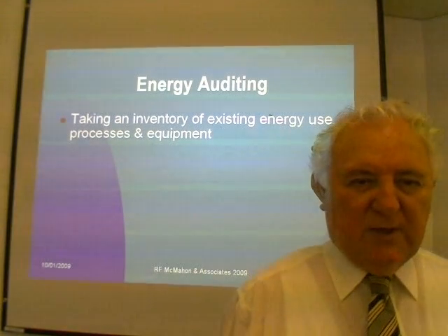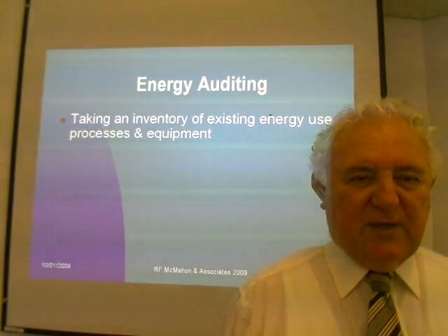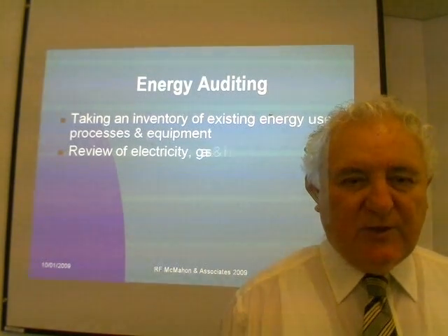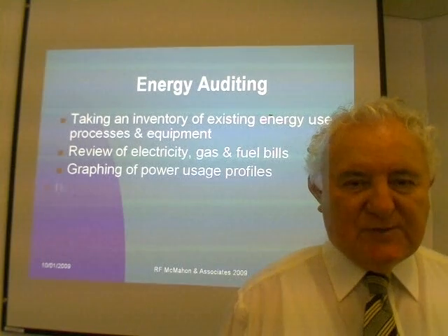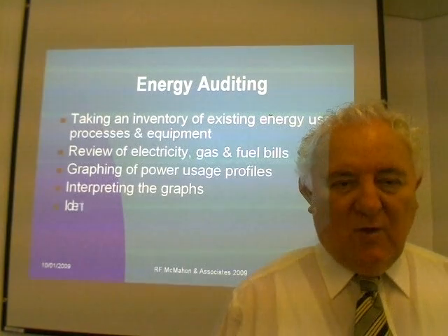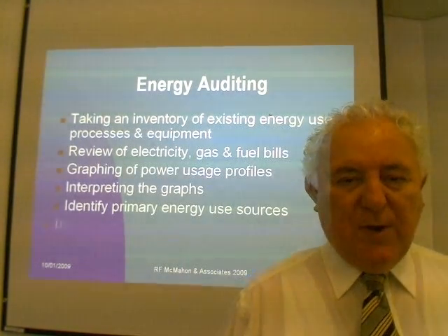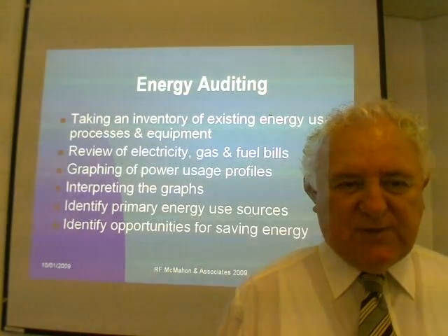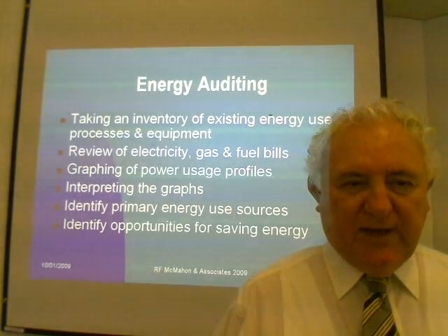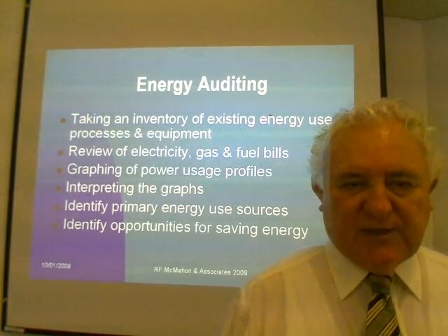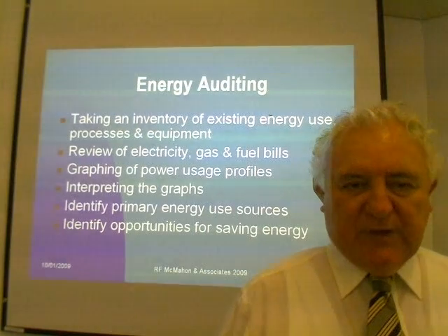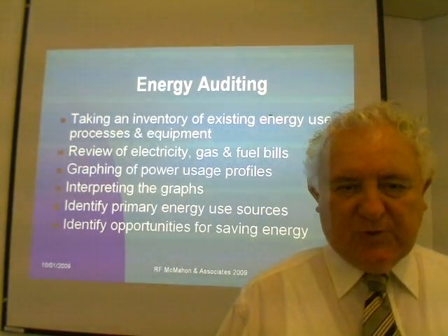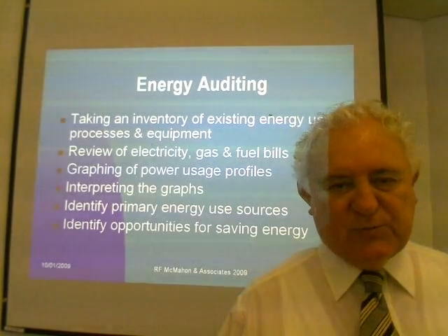Now, first thing in an energy audit is to take an inventory of all the existing plant and equipment in your facility. That means listing all the lighting, all the electric motors, all the plant, all the equipment, the hours that it runs, the size of the equipment. We do that. We review your electricity and gas and fuel bills. That means from the authorities or from the bills, we can get your bills for the last 2 or 3 years, as much as we can get.